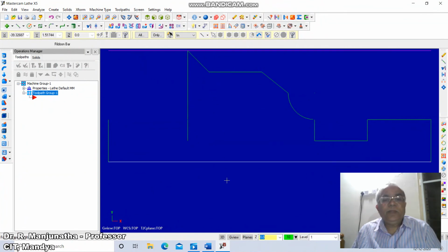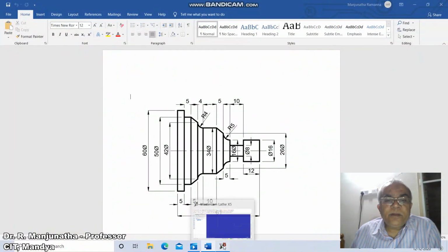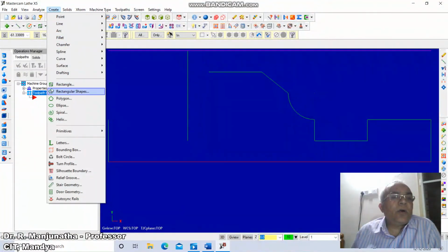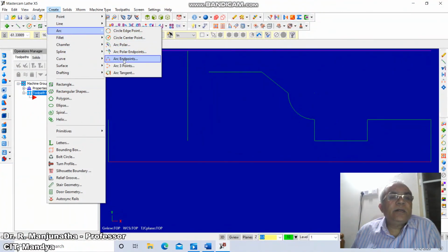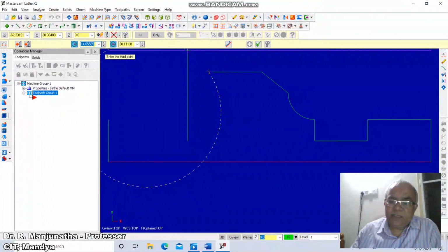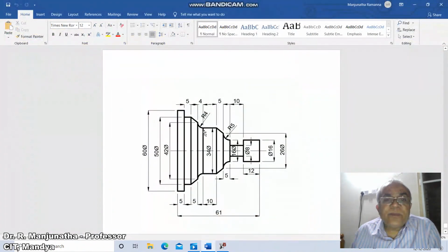No, it's that. So from this taper, you have, so here, this is the radius what we want, it's not the taper, we want the radius. So you just go to erase and erase this line, and go to arc, create arc, take the endpoint, take this endpoint, and with reference to this endpoint, take the radius as 4. So retain this arc. Then from this arc again you have a distance of 5 mm.